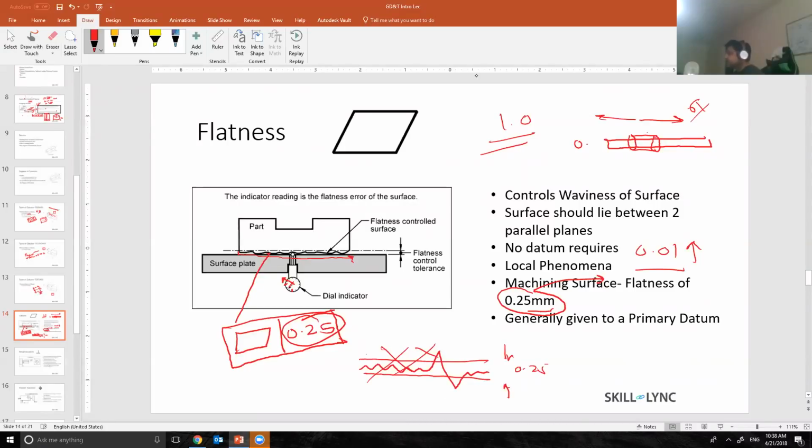But if it's a rigid part, for example, let's say I'm attaching a bracket to a transmission. In this case, I don't want the bracket to move. So basically, once I torque all these 4 bolts, I don't want the bracket to move in any direction. In this case, you have to constrain all 6 degrees of freedom. Again, it's based on the functional aspects of the part.